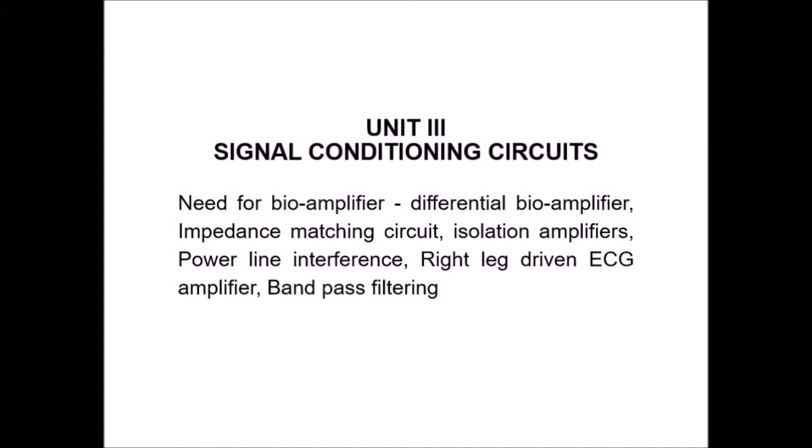In these signal conditioning circuits, there are different amplifiers that we are utilizing, and these amplifiers are nothing but operational amplifiers. Using these operational amplifiers, different circuits are designed: differential, impedance matching, isolation, power line interference. So these are the different circuits that are designed using the op-amp. How these circuits are utilized in biomedical instrumentation, we are going to discuss now.